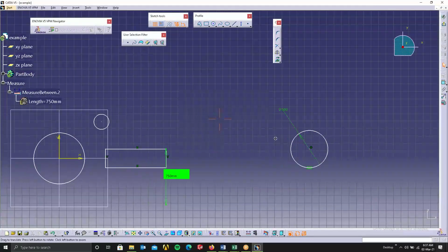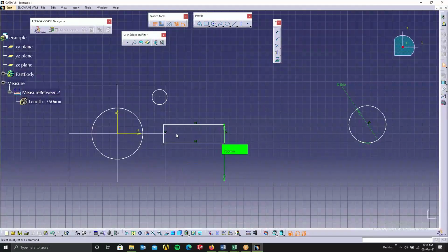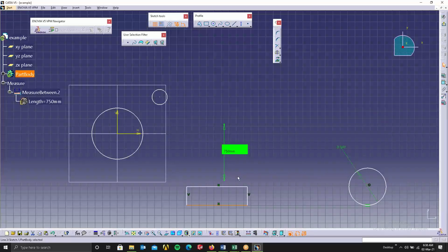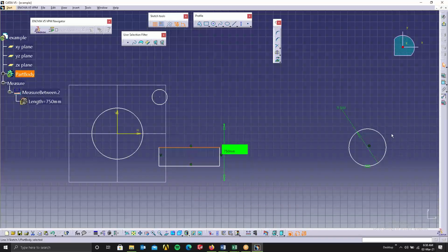This is one of the things that happens when your drawing is not constrained. The other thing is when you're sharing this file with somebody else and he converts it, the drawing will automatically change. It'll shift a little to this side, because the computer is trying to process the information that is in some other computer. So it's beyond your control. That's why, no matter what you're doing, you should make sure your drawing is perfectly constrained.